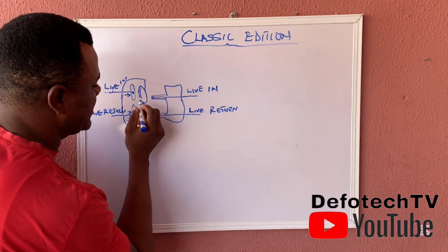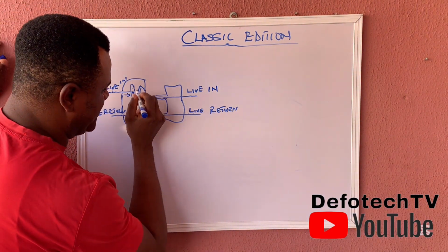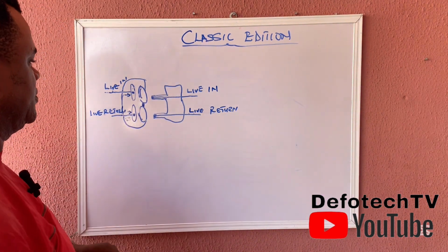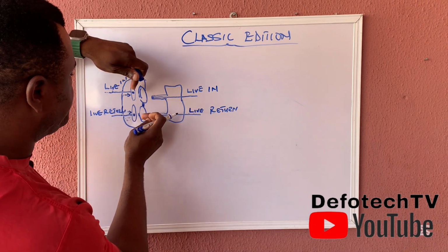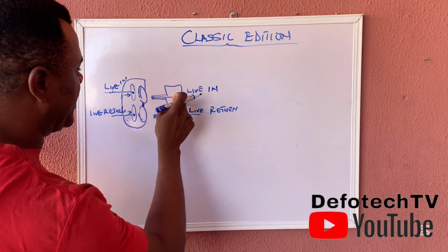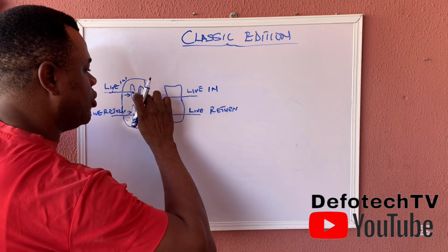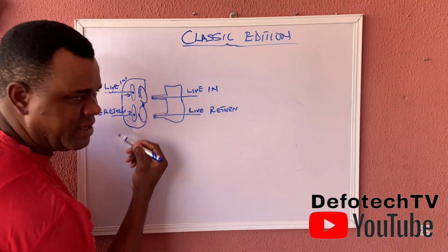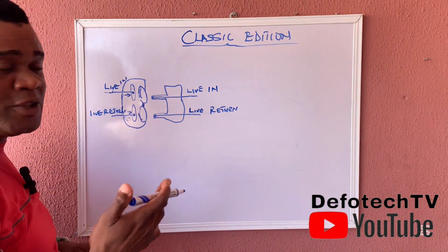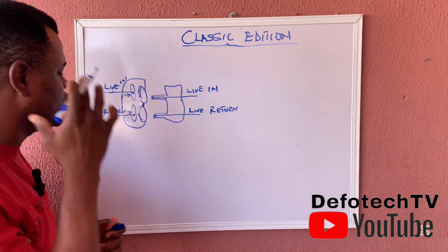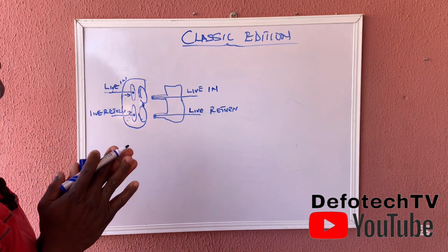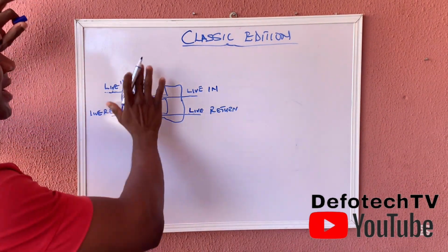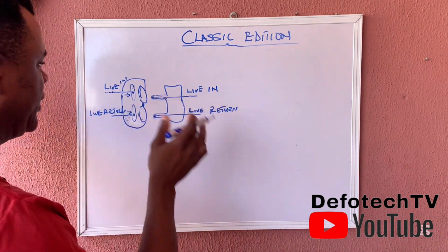Note that this one at the front here, there's a link between the upper circle and the lower circle. Anytime you push this gate contact, when the male comes in contact with this, it opens up from this contact, so there's no more contact between here and here. This is a typical gate contact, what it looks like. I want you to understand something first, so that when you're trying to connect to a fence, you know what you're dealing with. Before we talk about the fence, let's explain the gate contact and how it works.